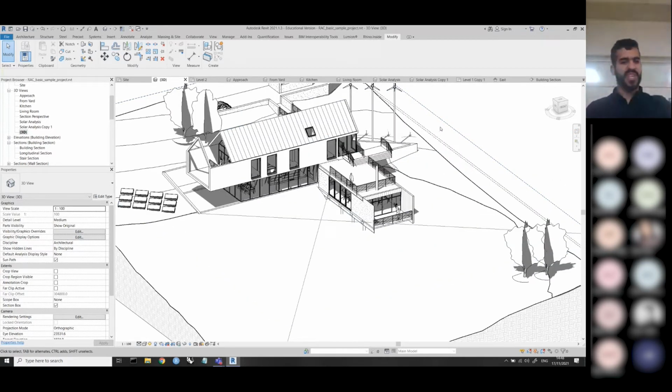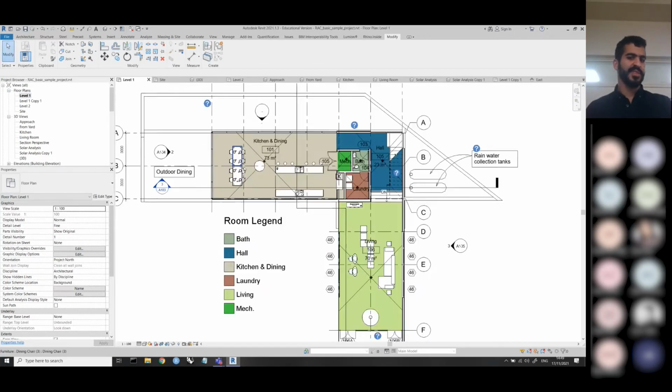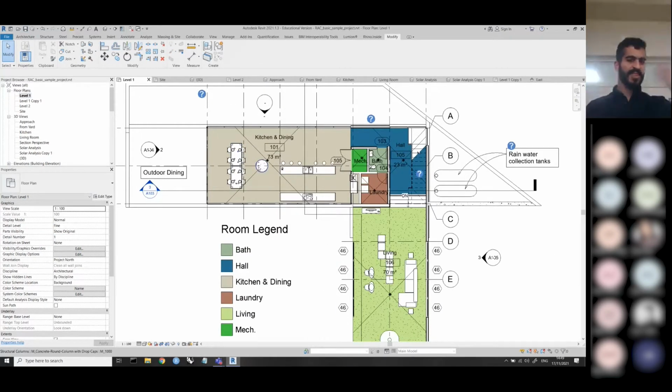Stairs are components you model, similar to windows and doors you put within walls. And these furniture are also components. So you bring them in. Revit has some existing components. The ones we see here, you'll find in Revit. You can just bring them in, it's fine. And if you can't find something, there's a lot online, think of SketchUp Warehouse, where you can download other models. You can download specific furniture, specific doors, specific anything, and just put it into your Revit, load it as a component, and then you can use it in your Revit model.